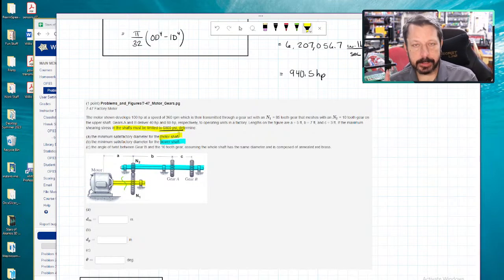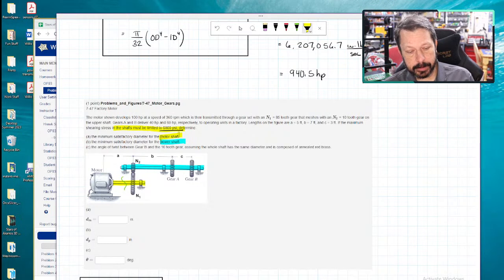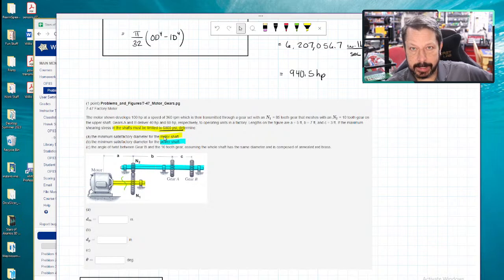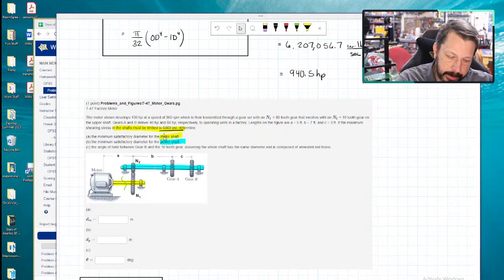So the difference here, so a couple of assumptions. Unless you're told that there's some efficiency loss, so this system is 85% efficient or something like that, then we're assuming that all of the input power, all 100 horsepower input, gets transmitted to the output. So all the 100 horsepower in the yellow shaft gets distributed to the cyan shaft. And that's unless we have some problem statement that includes the system is some percent efficient. In that case, which is more true in the real world, then if 100 horsepower goes in, we have an 80% efficient power transfer. Basically, that's between the two gears here.